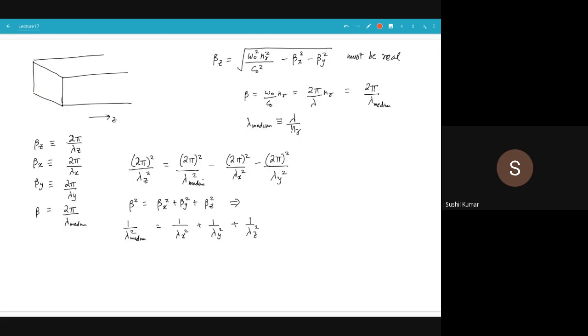If I launch this mode, for a particular mode there is some variation along x, right? You all know it goes up and down. That variation defines the wavelength along x, which I can call lambda x. As you mentioned one time, the first mode is half a wavelength, so lambda x is 2a in that case. When you have the TE20 mode, lambda x will be a.